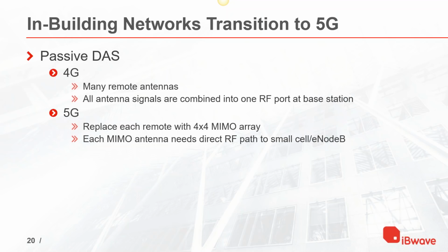And if you can imagine, that's quite a bit of change of philosophy from what we had prior, when we were combining all RF antenna paths into a single cable. Now we have to have dedicated cables from 4x4 MIMO into the base station.